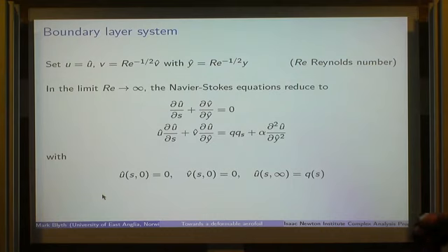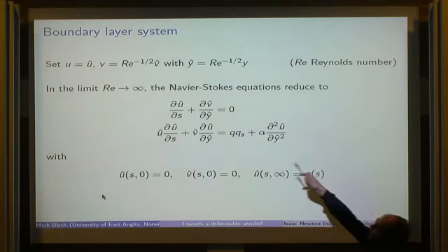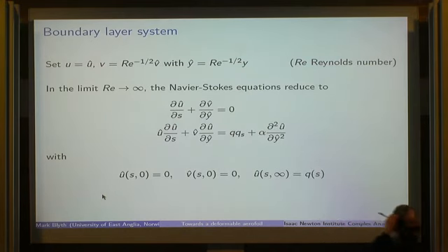So here's now we start to introduce viscosity into the talk. Here's the standard boundary layer scalings on a curved surface. So take Navier-Stokes, do the regular boundary layer scalings. Re is the Reynolds number. If you've not seen this before, these are just the standard scalings for the Prandtl boundary layer. And Navier-Stokes reduced down to this parabolic system of equations here. Little q is the slip velocity that we've computed, the potential flow speed on the surface of the cell. And the question is, little q as a function of s such that this boundary layer wants to separate?